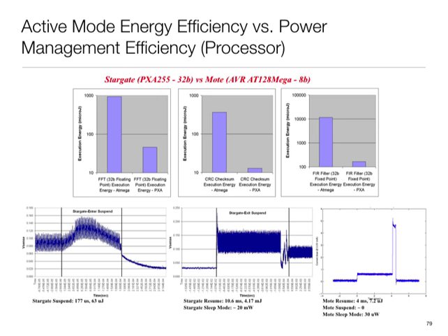So this is basically showing some extreme cases of a simple processor and a complicated processor, doing certain computations: FFT, cyclic redundancy check, and a FIR filter. What you see here is that the big processor, which is the shorter curves, is orders of magnitude, 10x or more, more efficient, because these are computationally complicated tasks. On the other hand, the big processor takes a hit because its transition times are larger, due to a combination of more complicated hardware and more complex state on the software side of things.